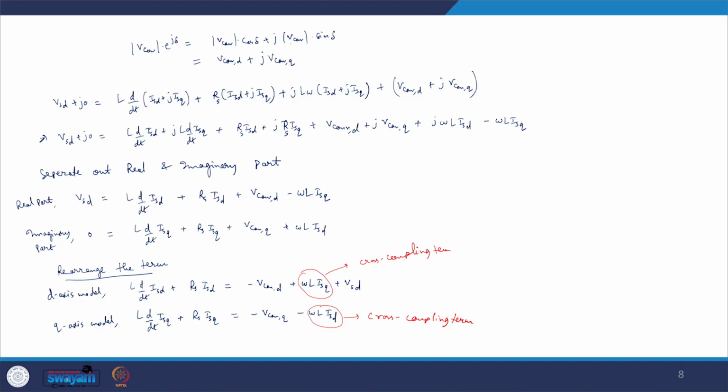So whenever you are controlling the D and Q axis components independently, it will actually reflect onto the three phase quantities in equal proportion, and that is when you can do the independent control. We will discuss more inferences coming out of this derivation in the next class, because that will clear your understanding about how we can do the independent control and how we can say they are independent of each other.